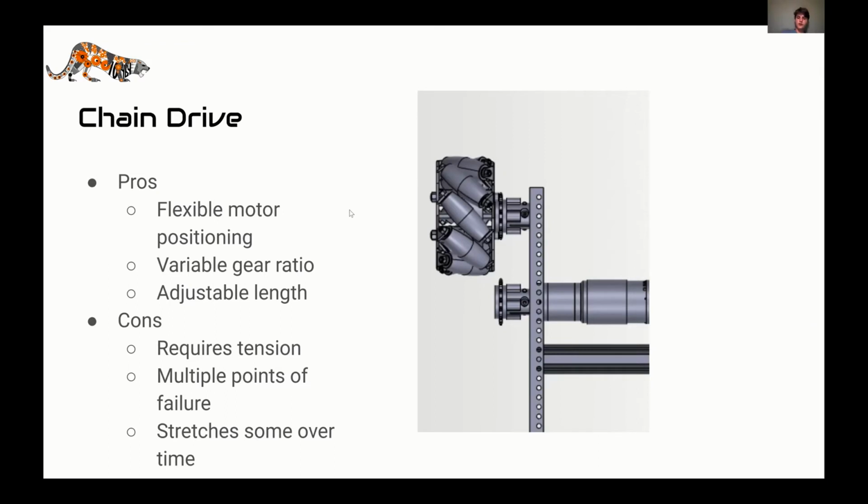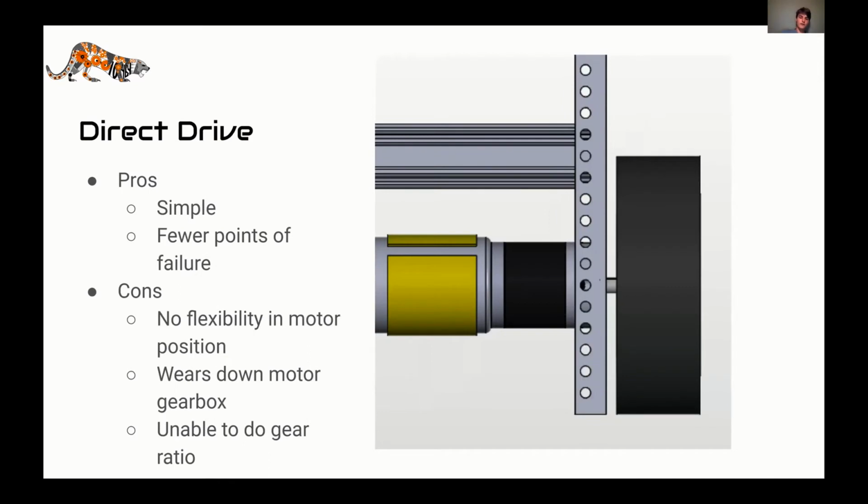And just something to note real fast about chains and chain stretch. Chain stretch is something that in a lot of our past cases we've kind of discounted, but what happens is the individual links will wear a little bit, but over a long chain that compounds. So you just have to keep that in mind and make sure that you have a tensioning system that you can adjust to account for all of that.